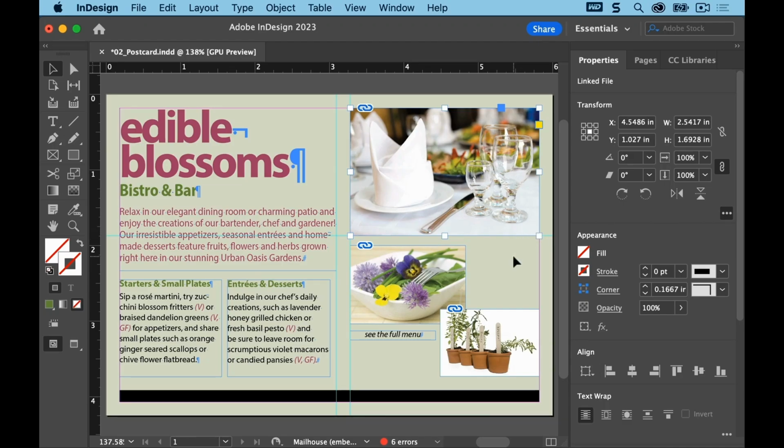You will now experiment with cropping a graphic by decreasing the size of the frame. And you will try moving the graphic within the frame. You will then undo these changes. Using the selection tool, select the middle handle at the bottom of the graphics frame and drag it up. You can crop the image by dragging any of its 8 resizing handles.